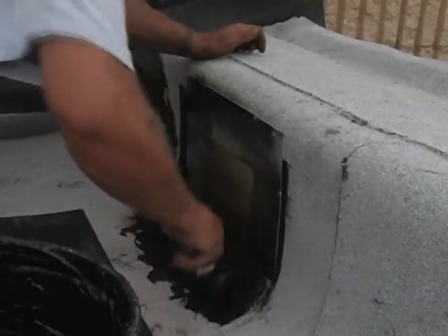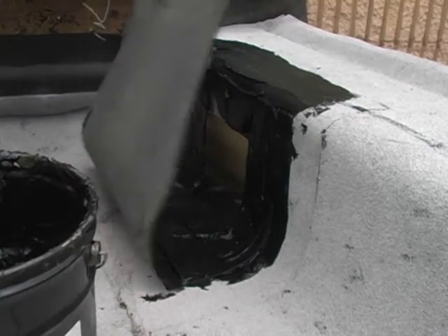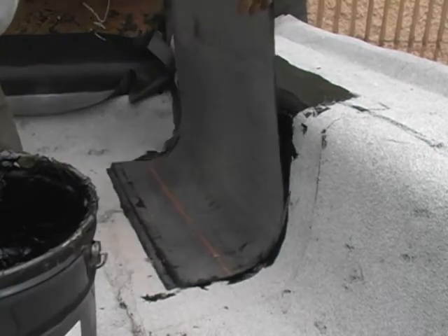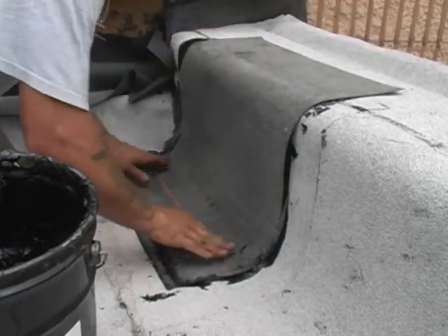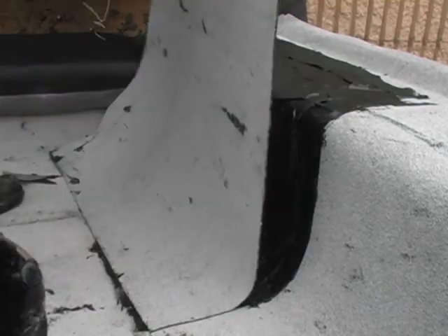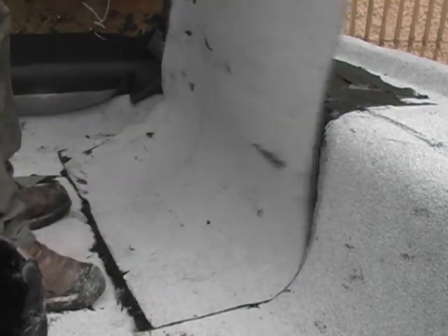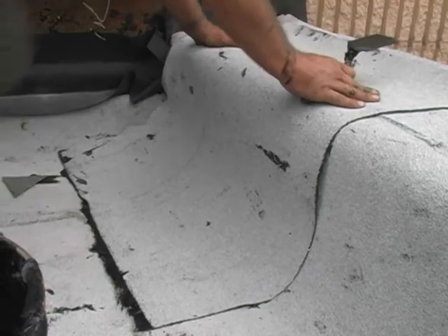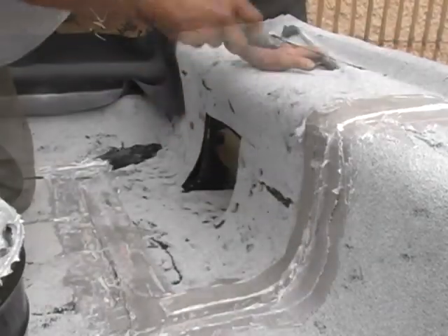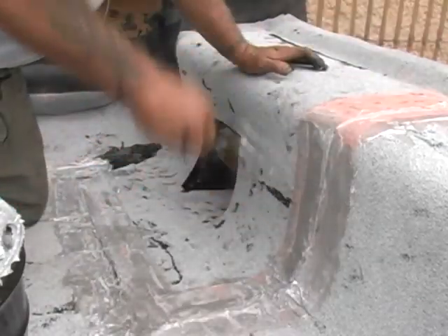Strip in flange of scupper box with base flashing ply covering entire area with 6-inch overlap onto the field of the roof and wall flashing. Install a second layer of modified flashing ply and bitumen over the base, 9 inches onto the field of the roof. Apply a 3-course application of mastic and mesh at all seams.